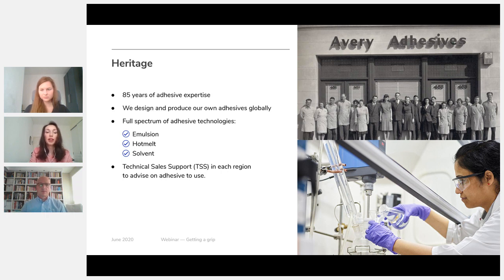That one basically is non-water whitening under any condition. Yeah, thank you, Renee. Also, an important point to mention is that it has been the case in the last years. It shouldn't be the case anymore, but ensuring that you have air knives on the bottling line is critical because adhesive doesn't like water normally. And then you can create the issues of water whitening potentially. So you really need to ensure that you have these air knives to blow off this moisture, and then the labeling should be easier. So maybe sometimes it's not the trick of a label, but the trick of adjustment of the equipment that is in place that you need to look at. Okay, what else do we have?